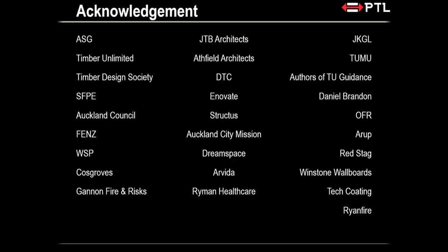Don't you have to get your screws from Germany anyway, so what difference? Shelf life, is it? The shelf life of the fire rated adhesive. They don't last that long. The screw will last quite a while. I hope screw lasts a bit longer. They also have problems with the fire testing, right? Like they just spent like 10 years of fire testing, like normal PURs, and now you go change your glue, and all your fire tests are essentially void.